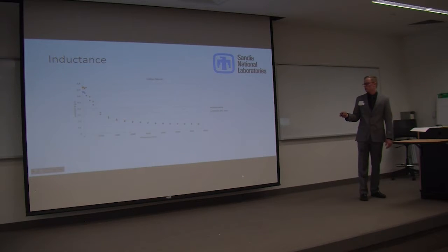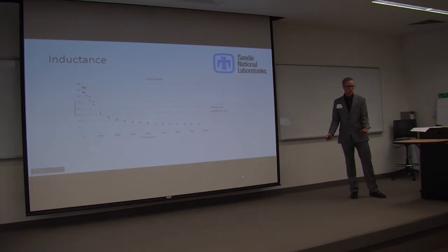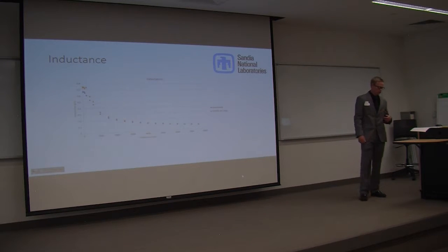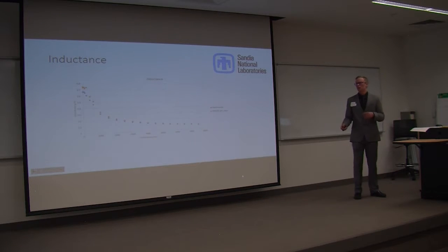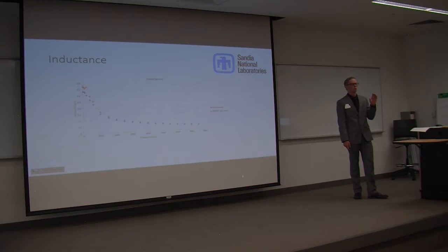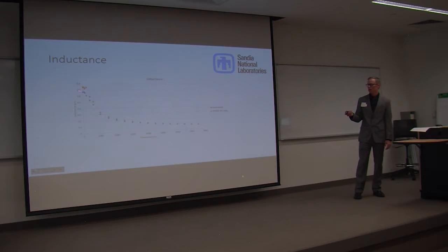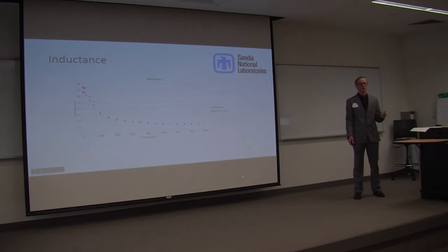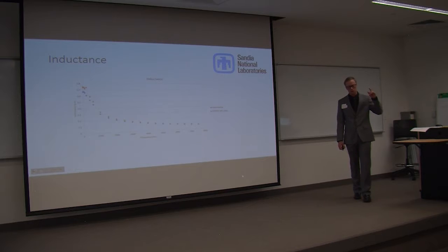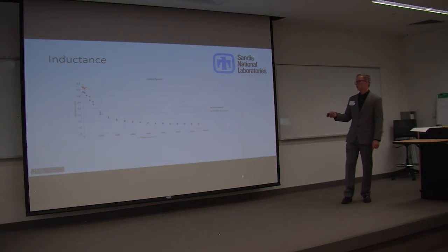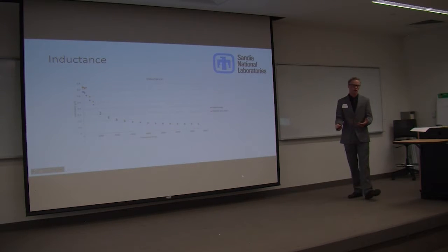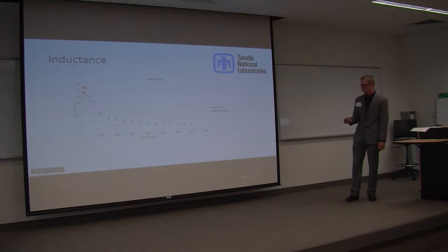And so it converges quite well, but we want to also look at why the physics works. Using a formula from the labs, it's basically dependent on the real permeability. The real permeability is the highest at 1 kilohertz, and as we decrease the frequency, the real permeability decreases, thus decreasing the slope of the graph and matching our results.